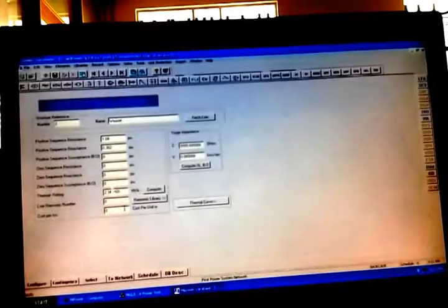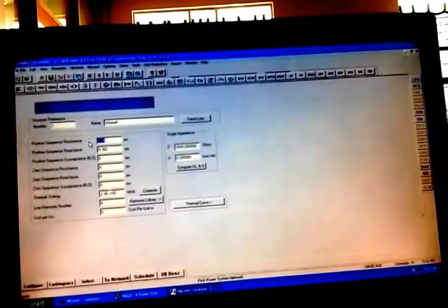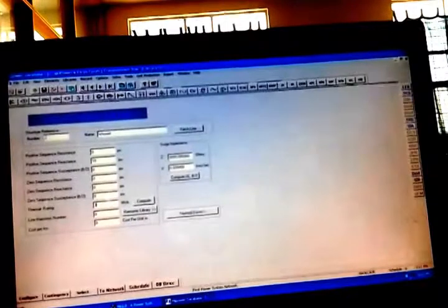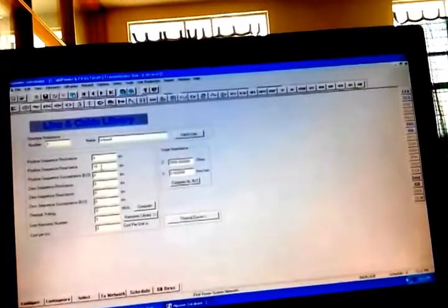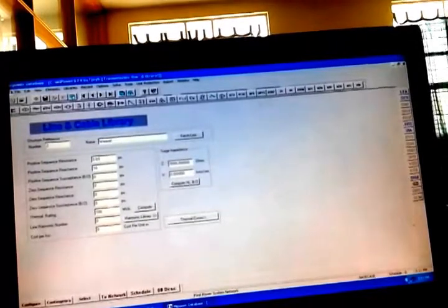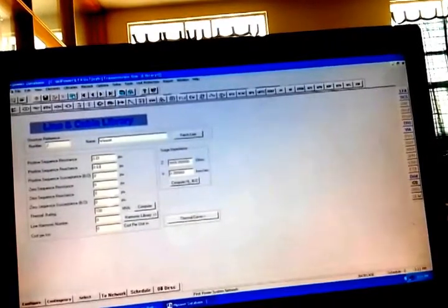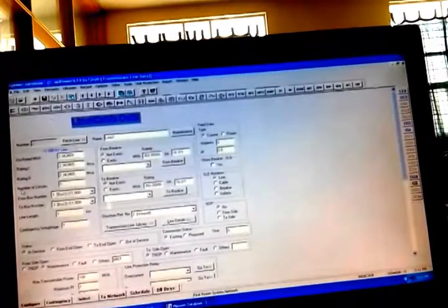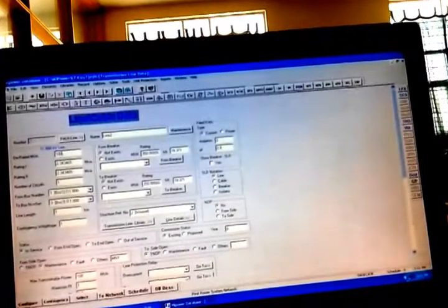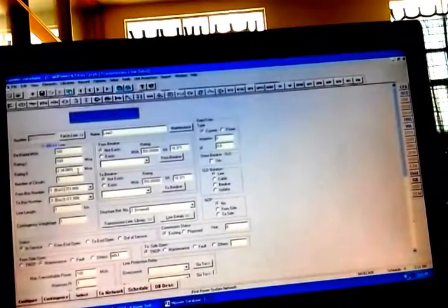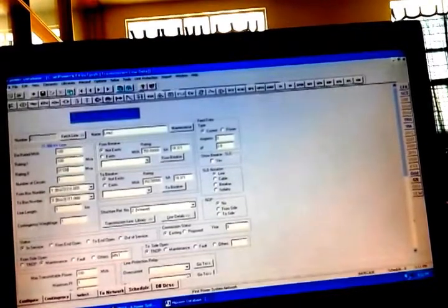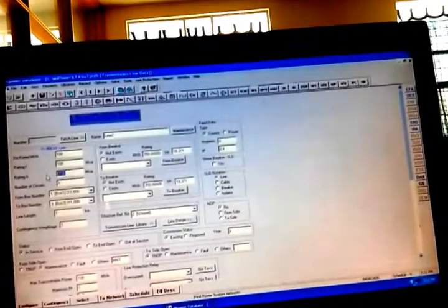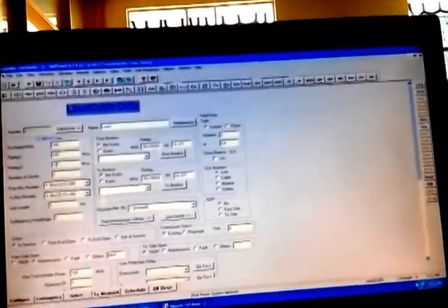Then go to transmission line library. Now you have the positive sequence resistance with different data as 0.01 and 0.03 and then thermal rating 100. Then save this, close this, then derated MVA 100, here also 100. Okay, now save it.